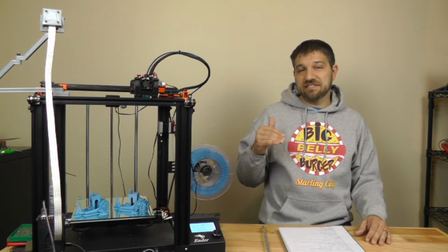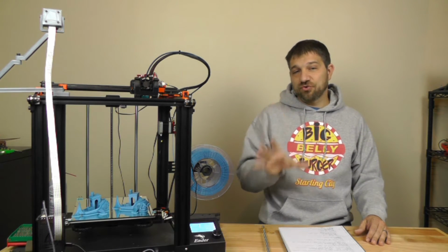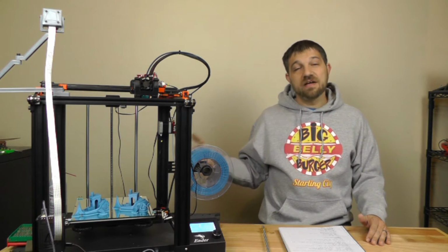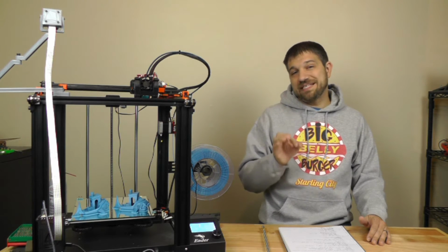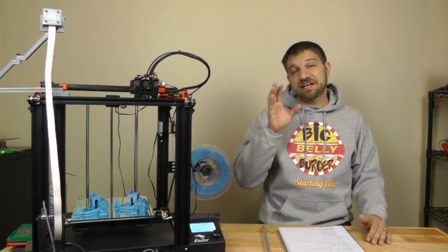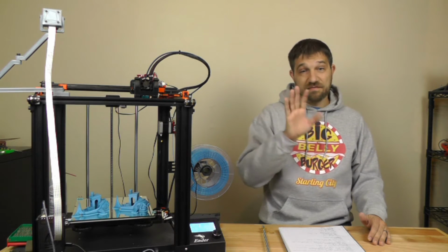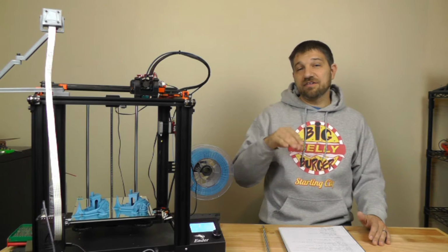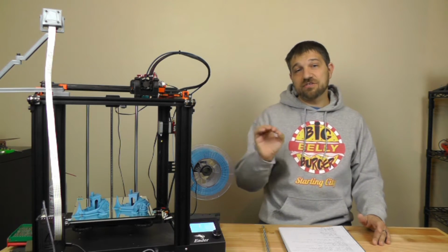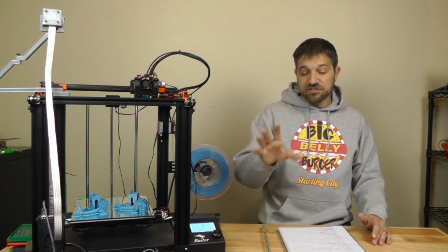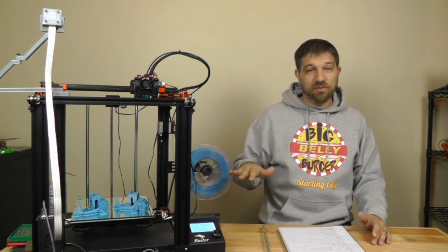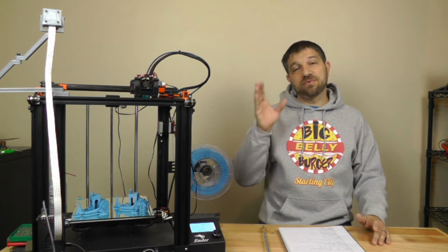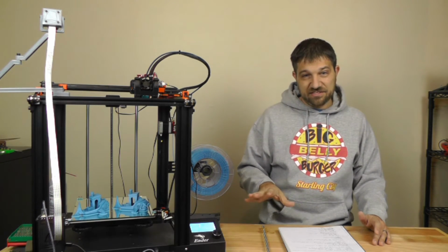So later after the installation, I'm going to show you how that increased steps per millimeter not only translates into the bed not falling, but possibly is going to buy us increased accuracy of our prints. And we're going to actually test that when we're all done. First of all, let's get to swapping out the lead screw. I'm not only going to show you how to swap this out, but I'm also going to show you a proper way to lubricate your lead screw before we ever get this on here, so that once it's on here, it's ready to go and you will have a longer life out of that lead screw.